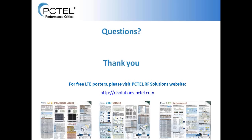And you're actually finding a lot of PIM also in building, because it depends upon where you place that antenna. Most buildings have a metal infrastructure, and they have ductwork. And if that antenna is not placed properly, you can actually have that antenna radiating the signal into that metal beam or into that piece of ductwork and causing PIM inside the building.